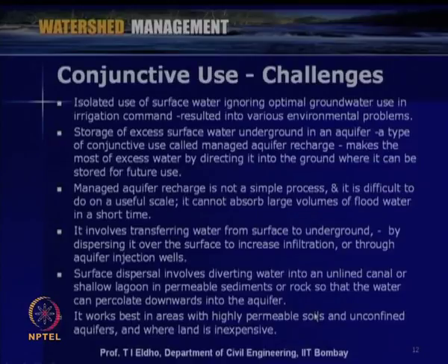So, as I mentioned, geology is one of the important factors as far as artificial recharge is concerned. Wherever highly permeable soil is there, it is easy to recharge the water, especially in unconfined aquifers. But for a confined aquifer, recharge is not so easy. We have to identify where the recharge area for the confined aquifer system is, or we have to go for infiltration through deep wells for recharging the confined aquifer system. So, these are some of the important challenges as far as the conjunctive use of surface water and groundwater is concerned.